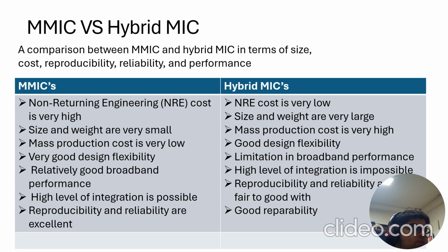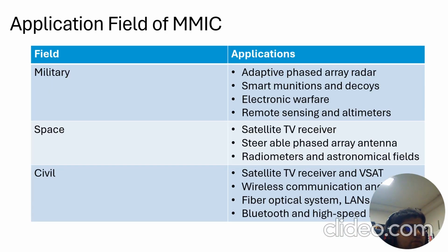For MMIC, there is very good design flexibility, good broadband performance, and a high level of integration is possible, and also reproducibility and reliability are excellent. But in the case of hybrid MMIC, there is a limitation in broadband performance, though a high level of integration is possible. Reproducibility and reliability are fair to good, and there is also good repairability.